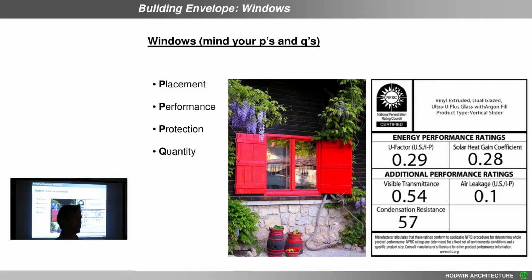The reason is because in the late afternoon, say 4 o'clock, the sun comes low in the sky, and the ambient air temperature is as high as at any point in the day. Both inside and outside of the house, it's warm. Let's say it's 80 degrees. The sun comes low in the sky, slides underneath the overhang, because it's really hard to control western sun in the late afternoon, and hits your west-facing windows.